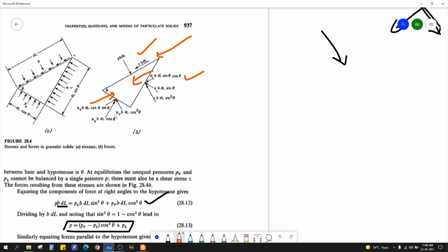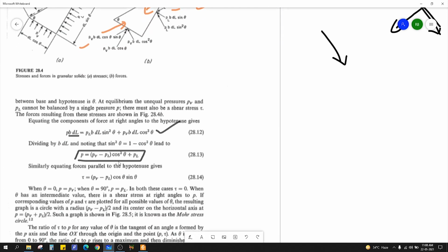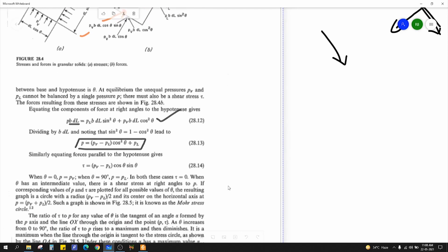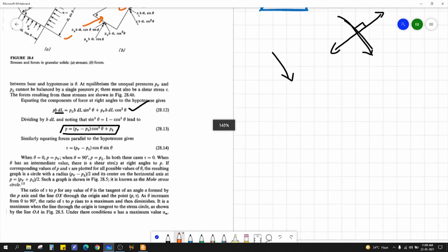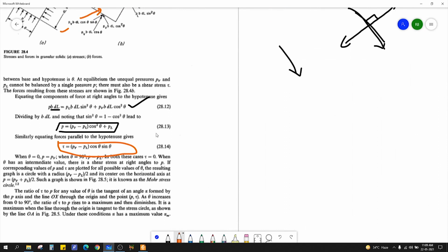So you have tau BDL, this plus this equal to this, because this is opposite, right? If you simplify, dividing by BDL only, you will get tau. Okay, there's PV minus. Fine. Now you have got this as well, right? Now I want to plot this on a graph. Okay, so what I will take is I will vary theta from 0 to whatever value, 180 or 360 degrees.